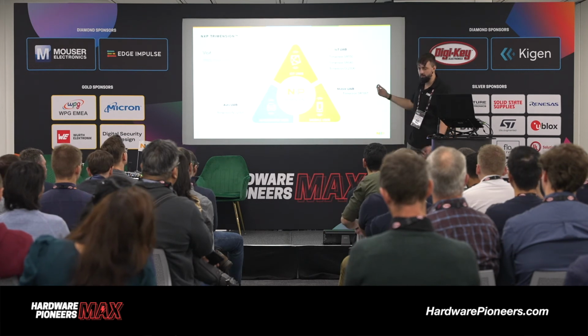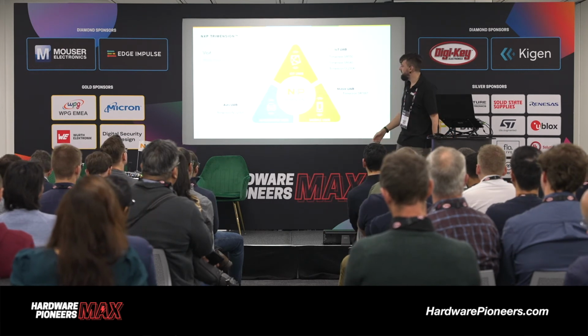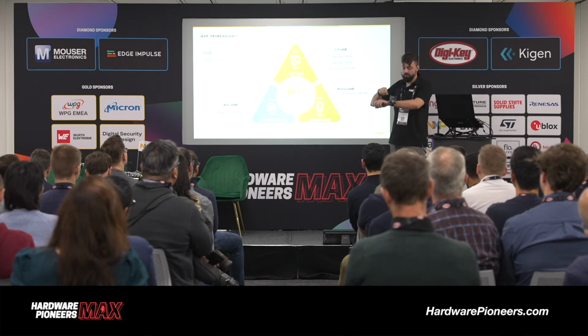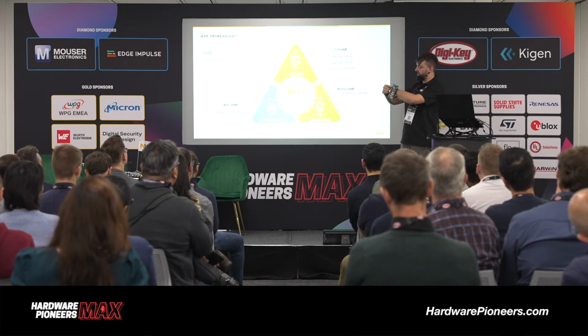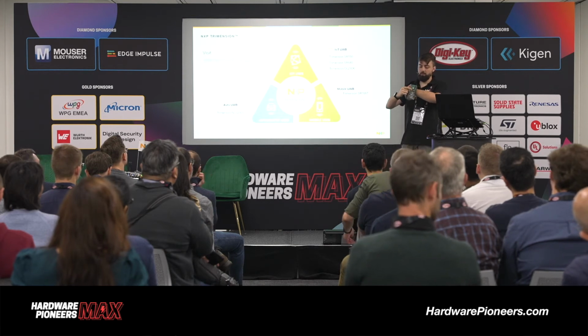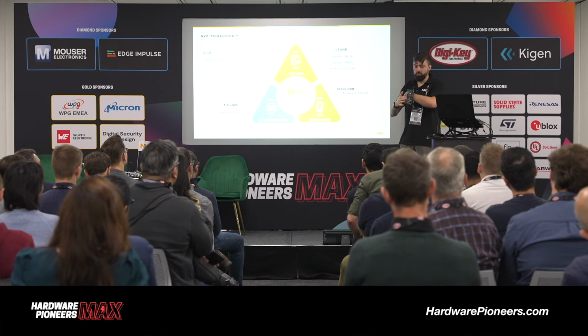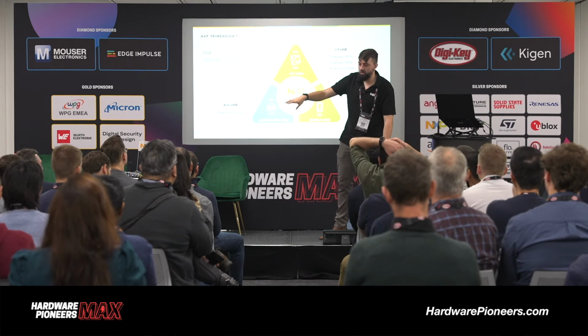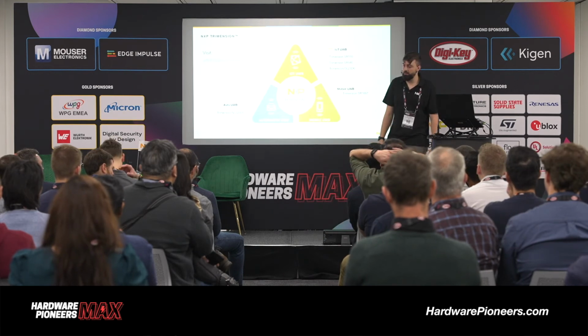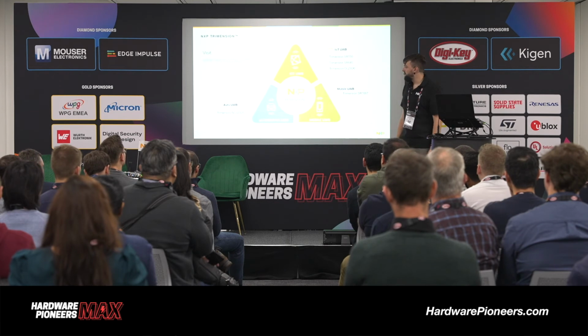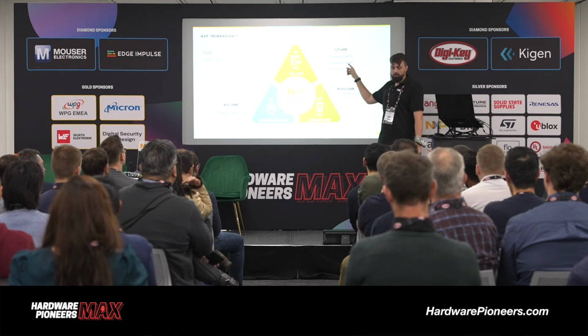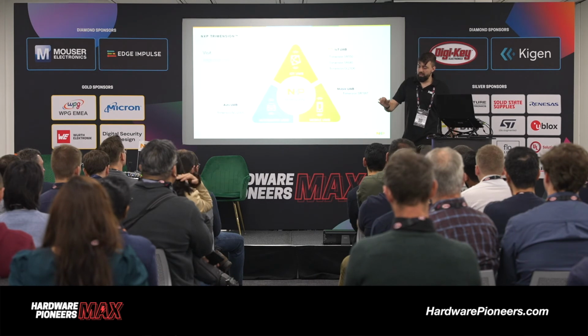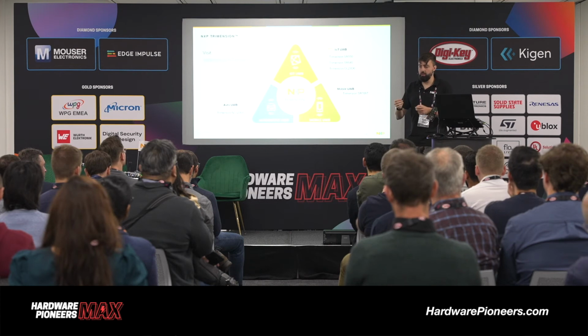Then for IoT, that's probably most interesting for you guys, we have the SR150, which is this chip. It's an ultra-wideband device which can have multiple antennas. So on here we have 2 antennas. On that chip we have 3 antennas with which you can do phase difference of arrival or whatever you want with multiple antennas. Then we also have the SR040, which is a low-power, small tag-like chip that can be integrated into tags similar to the Apple AirTag and used exactly the same.